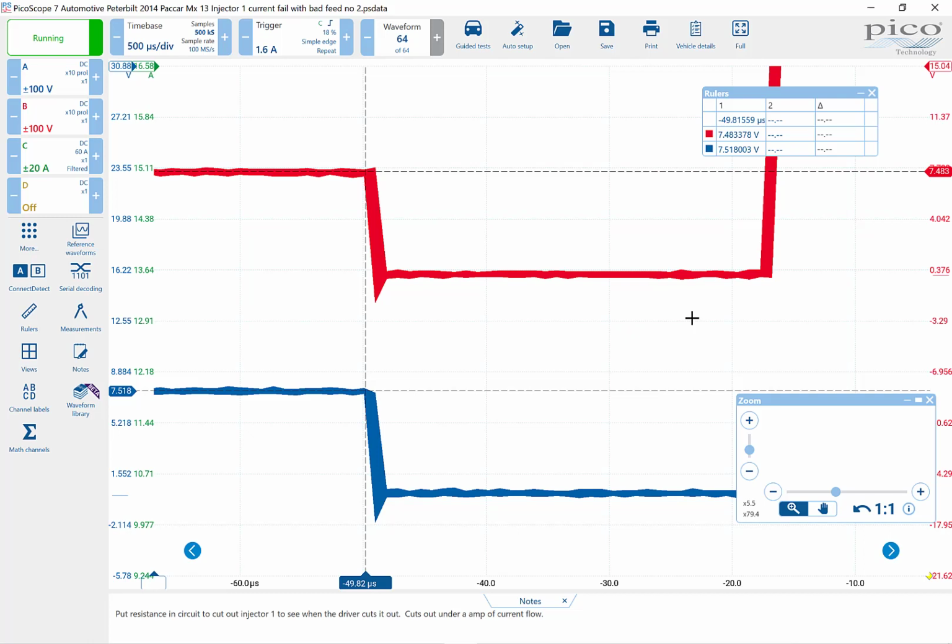So that's how these injectors work. And Cummins works pretty much the same way as well, okay? This is very good to know, because it can help you determine whether you have a driver that is failing inside your computer. You can also time this out with your cursors when it initially fires, and see how long it takes for that capacitor to dump, okay?